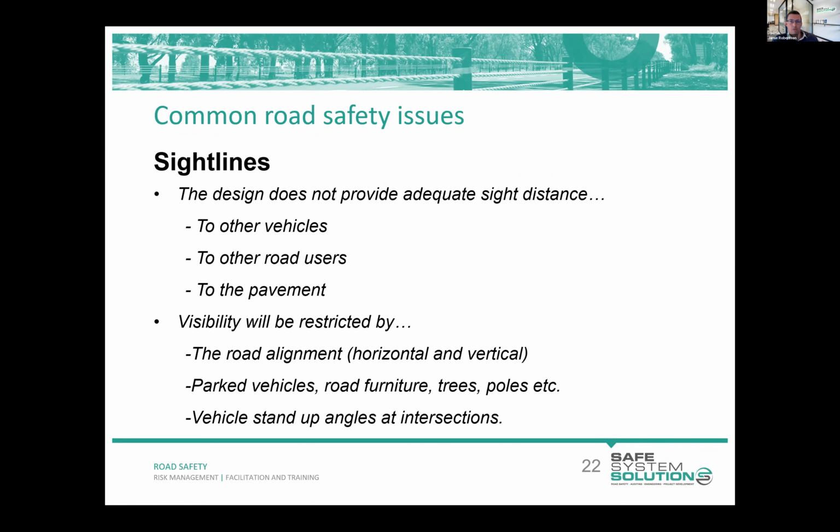Sight distance requirements may be measured from a driver eye height to the pavement, to an object on the road, to a part of a vehicle, such as a tail light or the top of an approaching vehicle. There's a whole suite of different sight distance requirements that it's important to have some familiarity with and to know where to look if you're reviewing those.